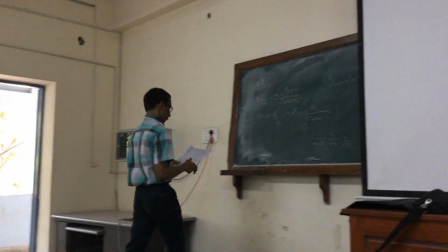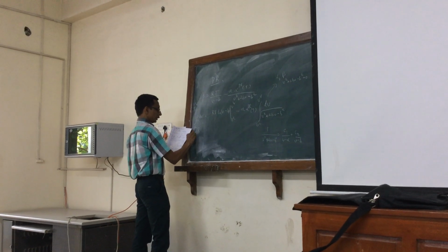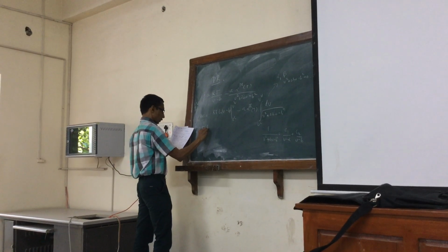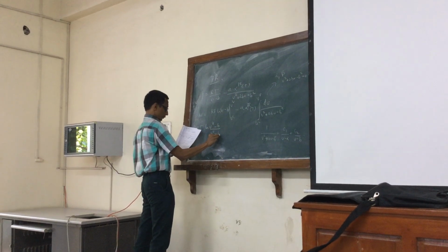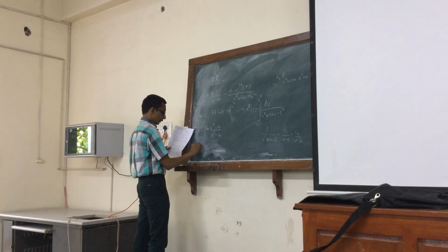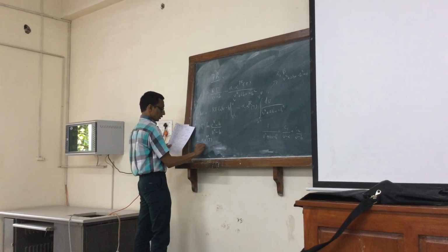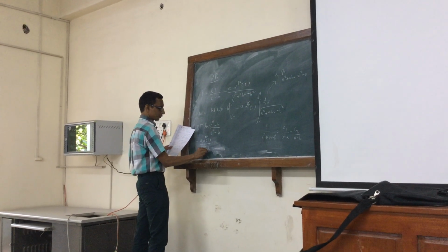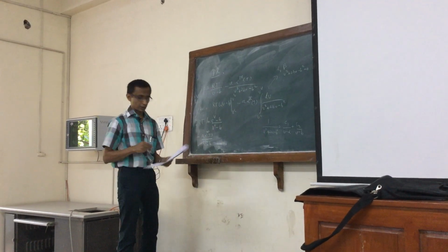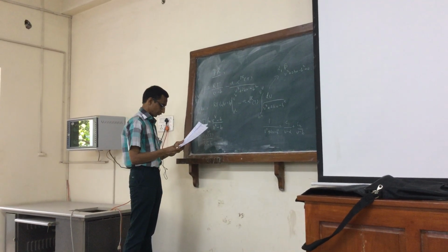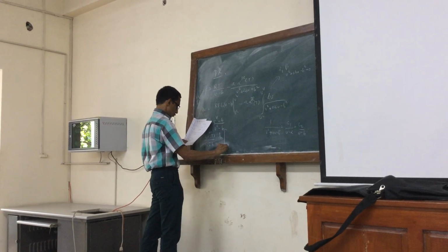Here you have to do a slightly longer calculation, but the answer you will get is RT integral, RT log (VV minus B) by (VL minus B), and then minus A times alpha of T. Then you get 2 root 2 B. This will come as coefficients. C1 and C2 will probably be the negative of each other. And then in the logarithm, you will get two factors.